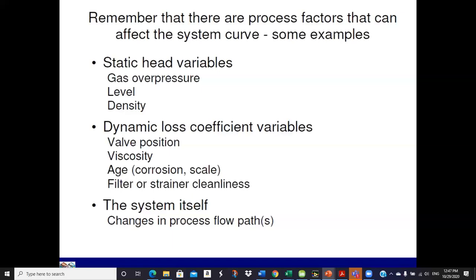You've got some different friction coefficient. And that's very common on older facilities, if it's a flow that can cause some sort of buildup to accumulate. Sometimes they have to go in and clean that stuff out. It'll get so bad they can't force enough fluid through it, and then they have to shut down and rinse it out, or put a pig down there, or somehow physically go in, or do a chemical cleaning to dissolve that stuff and get it out of there, so then you can operate the system again.